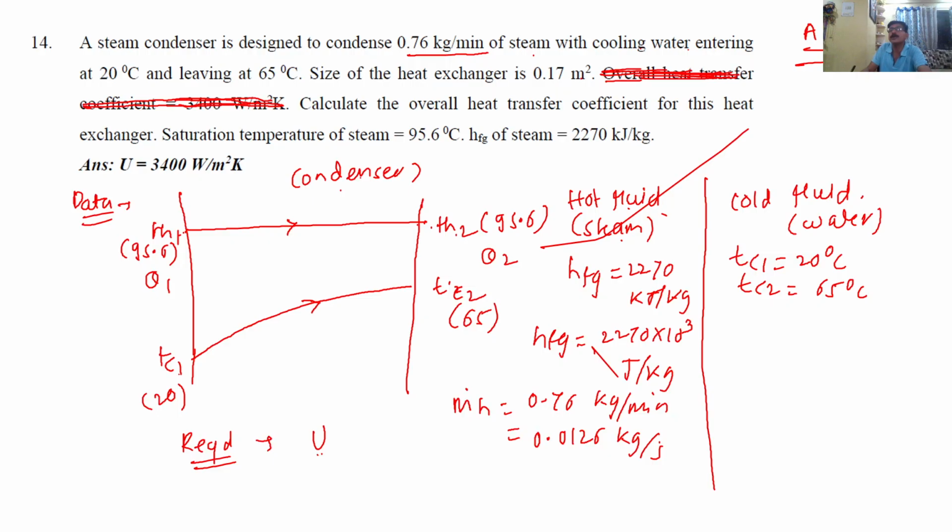It's very easy to understand because in every problem more or less I have repeated it. If 3 or 4 temperatures are known to you, you can use the LMTD approach because that is the best approach. You can use epsilon NTU also, but the LMTD method is the easier one, and that's why we use it. But if 2 temperatures are known and 2 temperatures are unknown, then compulsorily you have to go by the effectiveness NTU approach, that is the epsilon NTU approach. You can't solve the problem by the LMTD method. Though LMTD is easy, we can't use it when 2 temperatures are unknown.